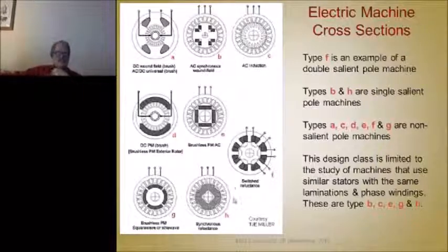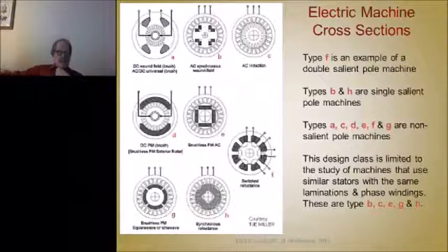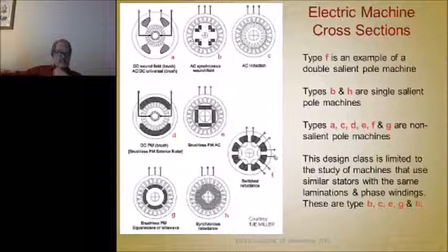And now here's an extreme example of a reluctance machine that has poles that look like a gear on the rotor and poles that look like a gear on the stator. If you look at this winding here, the flux is going to go through there like that. There's very little air gap in the circuit. It's all iron, very tiny clearance gap there. But in this set of poles, there's lots of air gap in the circuit. You got this great big air gap in there. So the inductance here is very low, and the inductance there is very high. There again, we're in quadrature here.